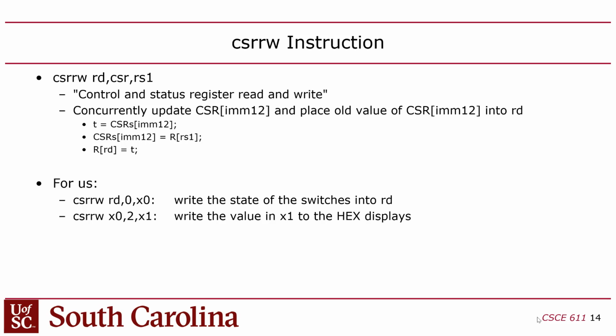You've got a vector of 8 elements inside here, and in one instruction you can push those out to the 7-segment displays. But again, you have to use your decoders though. Your decoders are an integral part of this, because otherwise you're right, you wouldn't have enough bits. You'd need 56 bits to do it. Likewise, this value you'll read in the switches, now there's only 18 switches. So you're going to have 14 zeros and then 18 bits from the switches.